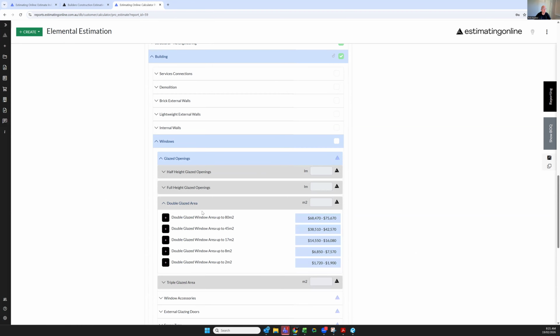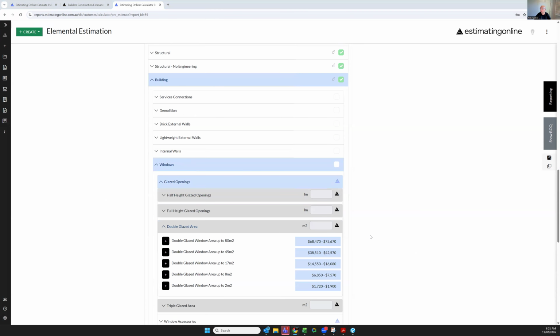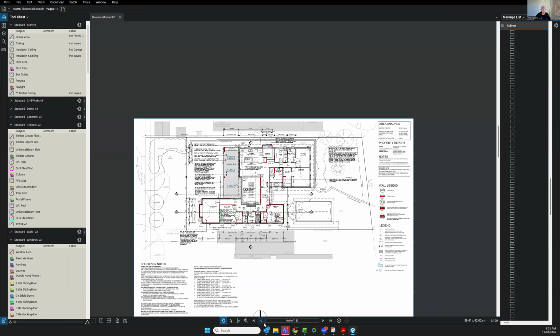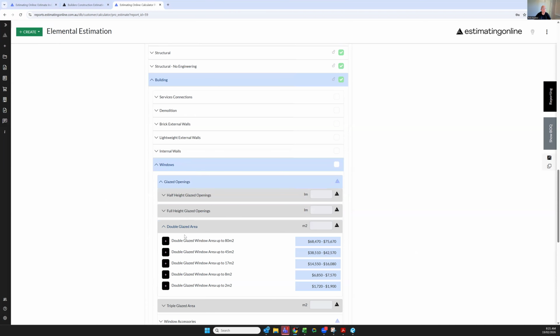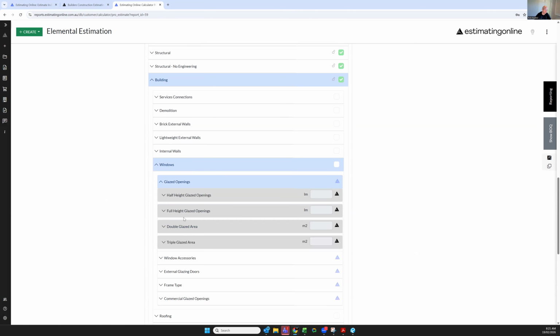What we can do is work out the square meters by using a measuring tool and calculating the area. Or we can actually do windows a different way for a takeoff. Once again, our goal is to make sure that we have more square meters. We need to take into consideration waste, minimum charges, and how glass is purchased. So if we take estimating from the surface and put in the actual perfect square meters, we're potentially putting ourselves in a situation to lose.